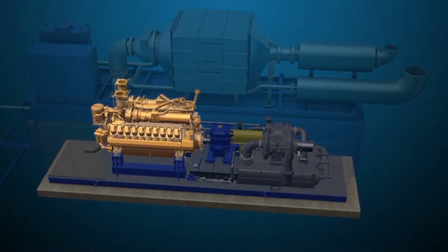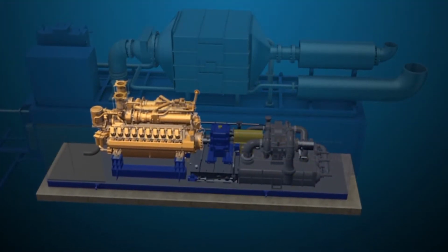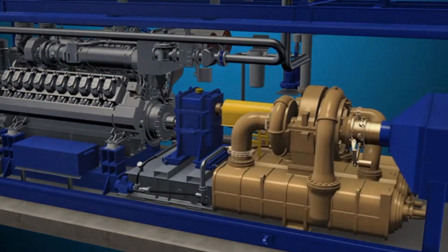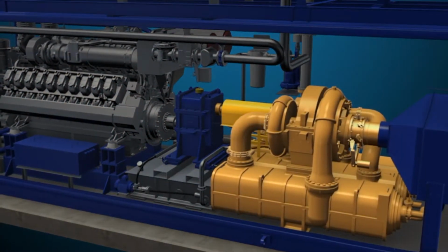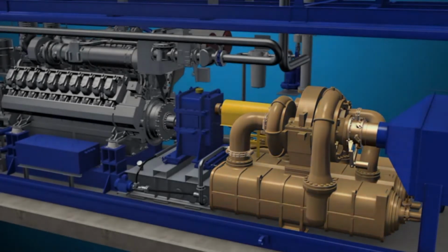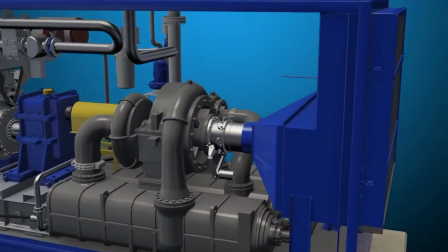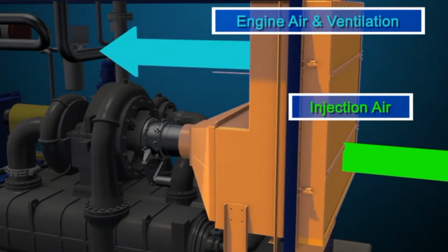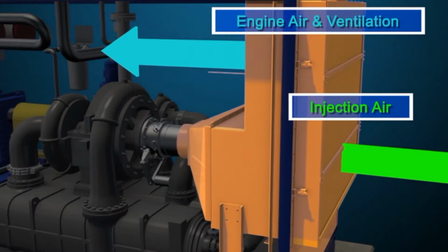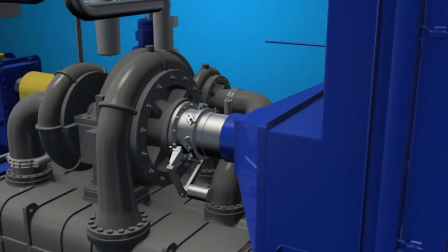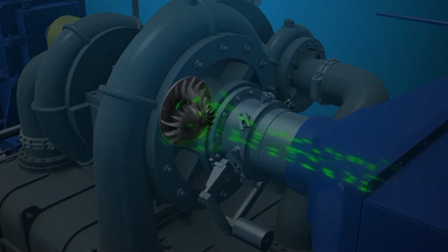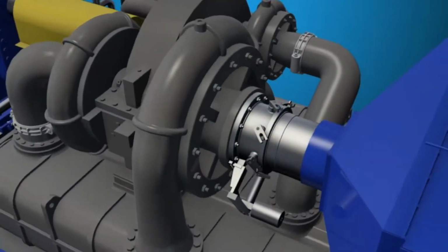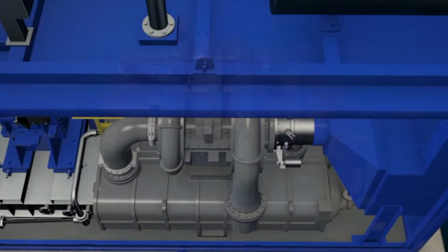Turbophase is a packaged system with a reciprocating engine driving a multi-stage intercooled centrifugal air compressor. Air is drawn into the system to ventilate the system and provide air to the compressor. The compressor air filtration system mirrors the air quality of the gas turbine, and the air is then compressed by the first stage of the air compressor and then cooled.